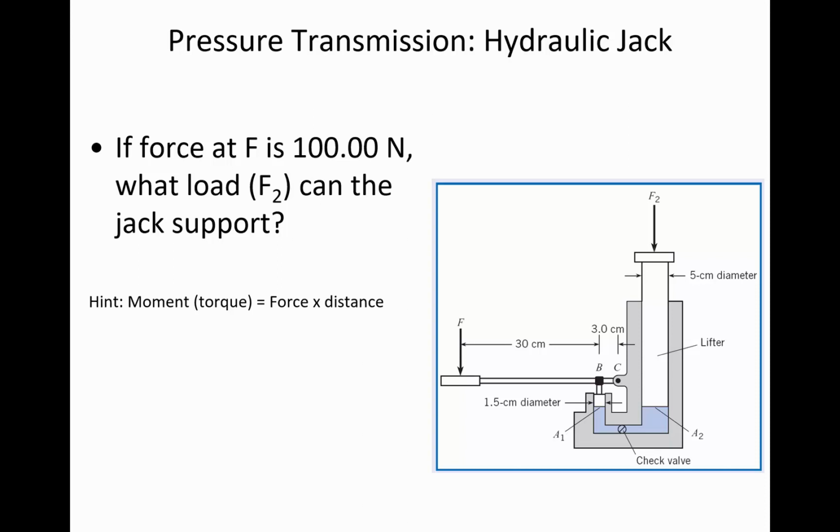Okay, first of all, if you're taking a bulleted list, part 1 is find out what is the force acting at B. And you're going to do that through moment analysis. Then find the pressure in the fluid, because you're going to know a force and you can calculate the area. And I'll type the formula for area on the screen.